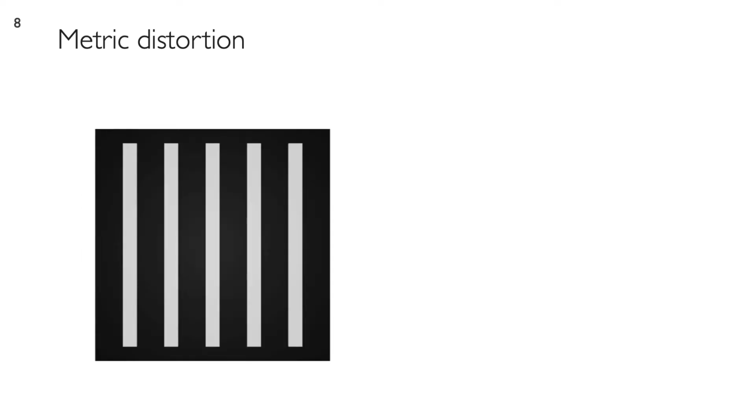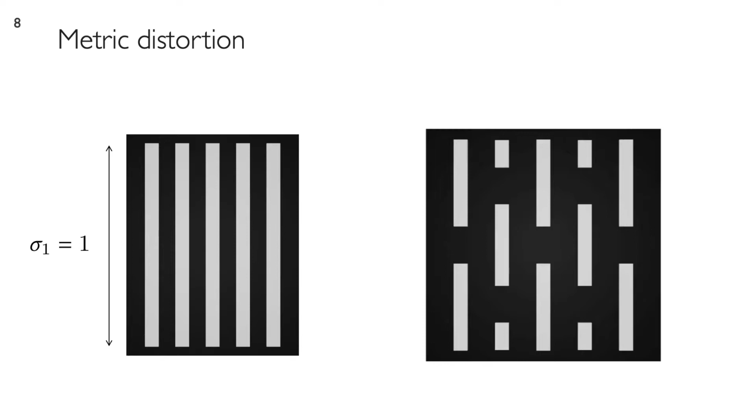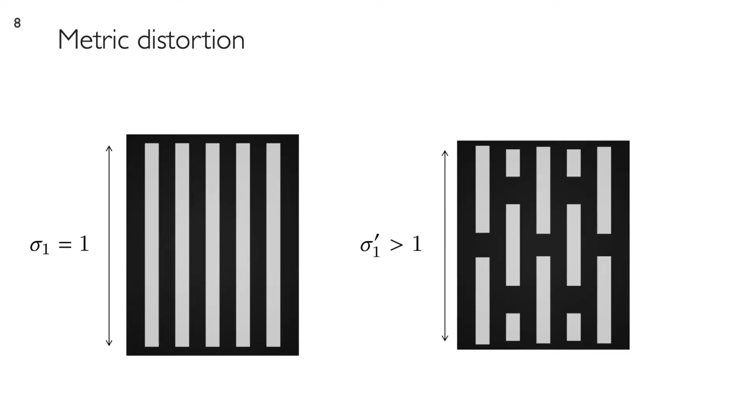As I mentioned, the distortion along continuous curves is equal to 1. It might be a bit constraining to force this distortion value to 1 everywhere, so a way to relax this problem is to print dashed lines instead to leave some space for the fabric to shrink. And to avoid creating weak structural points, we can lay out the curves in an alternating fashion so that the gaps don't align.